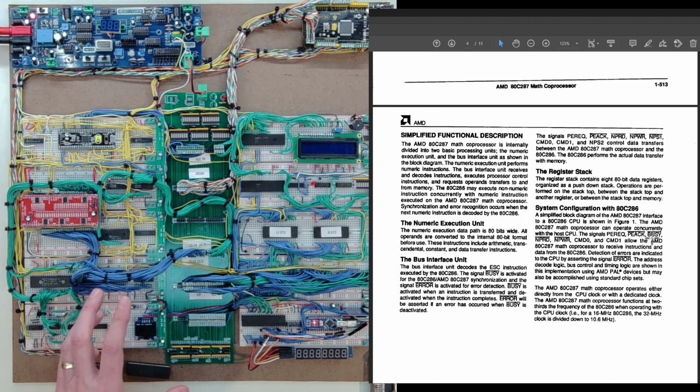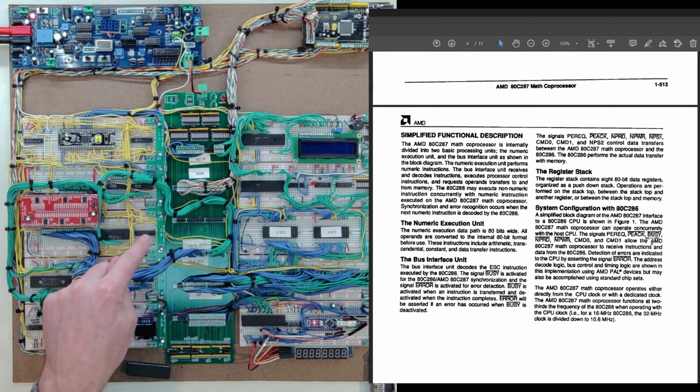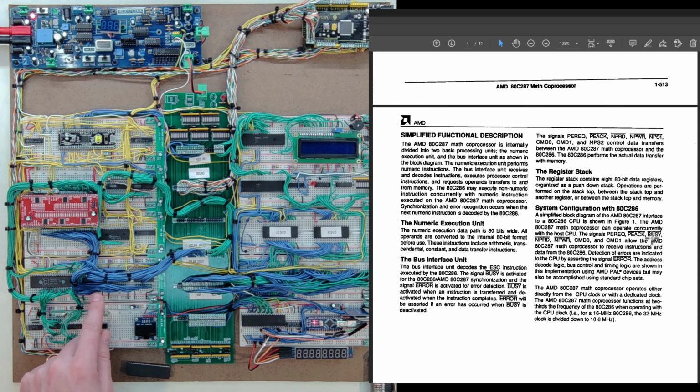So just for the fun of it, I took out all my HC chips, which would be 4 latches, 2 transceivers, and a NAND gate, and I put in AC versions. So I swapped out my HC with an AC, which is a little bit faster chip, but also may cause issues with those faster rise and fall times, as I understand it.